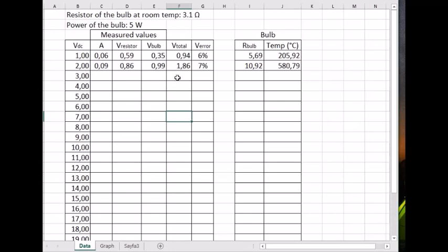First, you should calculate the measured terminal voltage applied by the source for each current value. Second, you will make a percentage error analysis with the applied and measured terminal voltages. This is for realizing the differences between the power supply and the multimeters. In addition, you will obtain the resistance of the bulb for each terminal voltage applied by the power supply.